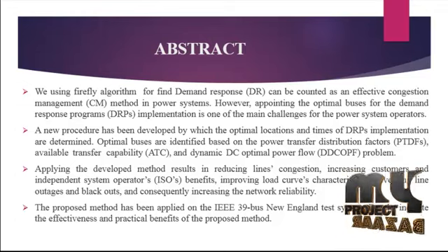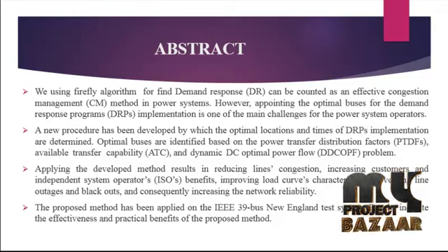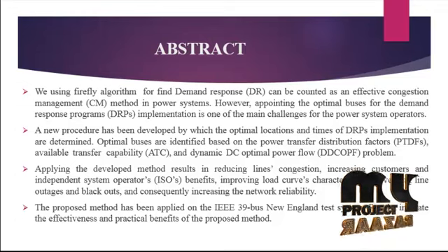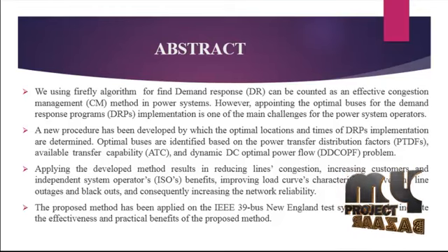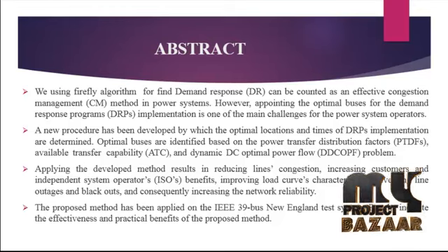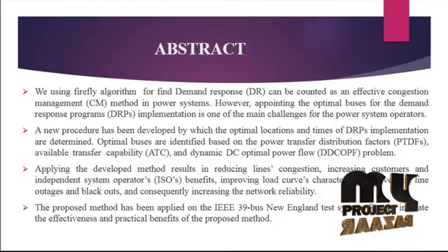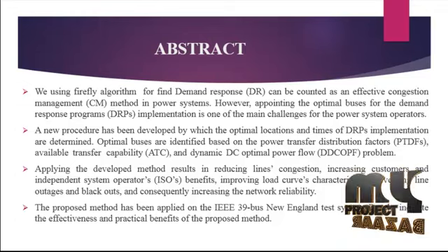We use the firefly algorithm to find the demand response that gives an effective congestion management method in a power system. Demand response programs are implemented as one of the main challenges for a power system operator. A new procedure has been developed by which the optimal locations and time of congestion management are implemented, with optimal buses identified based on power transfer distribution factor, available transfer capacity, and DC optimal power flow also.